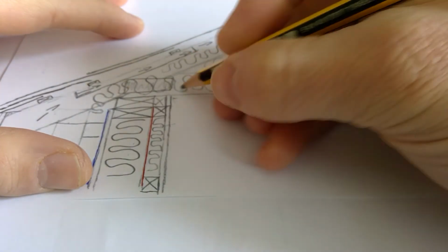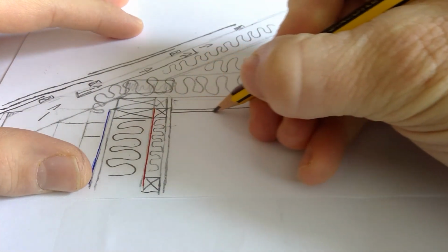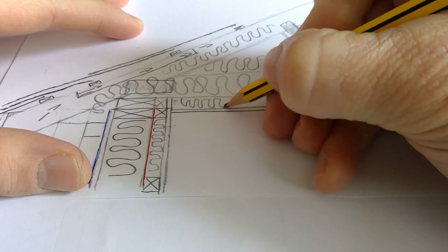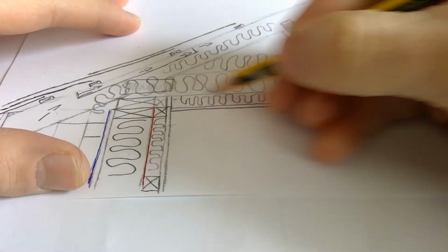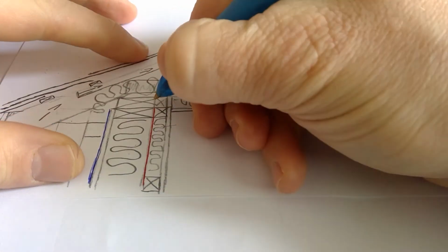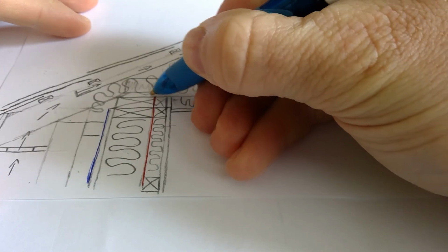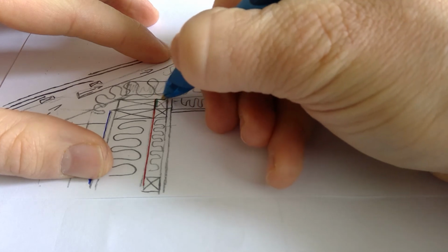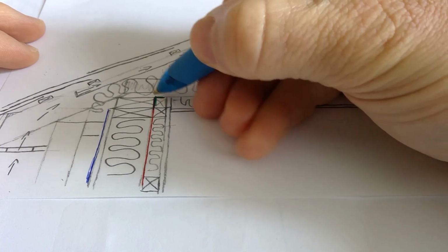Nowadays usually the plasterboard is insulated, so if you want to make a 50mm plasterboard you could. That is plasterboard there, and that's all insulation. It'll usually be rigid insulation, but that'll do fine. Now, how do we stop air from leaking out through this part here? Well, first of all, you have your air tightness membrane, that red line along there. Okay, but to stop air from sneaking out past that, you would have air tightness tape in the corner. It's taping the junction, so no air can escape out through there.